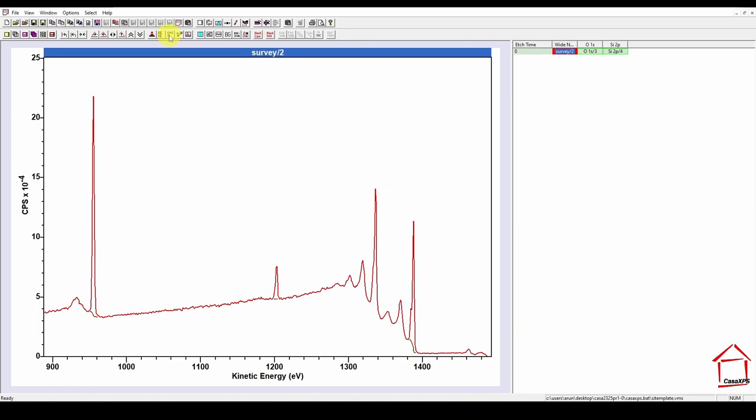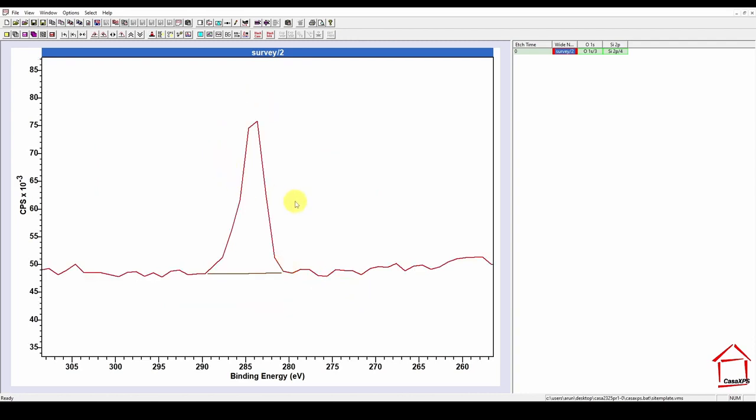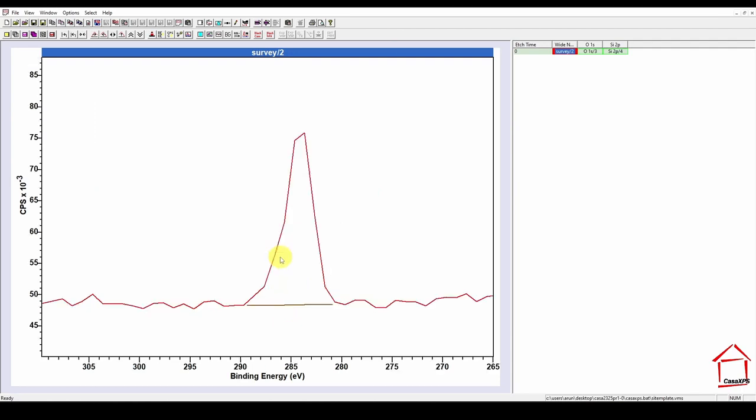And if you want to see this spectral line in a zoomed view, you have to draw a rectangle here, clicking the left button of the mouse and dragging, and click inside this box, so it will be zoomed. To zoom out you can use this button, that is the reset button. To zoom, you just draw a rectangle over that particular peak, then click inside it. So you'll get a zoomed view of the spectrum. And to reset, you can click here, that is the reset button.